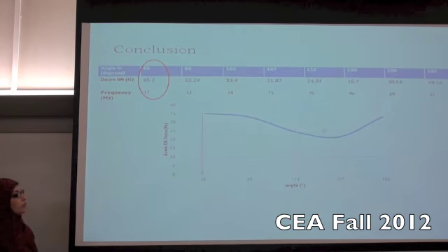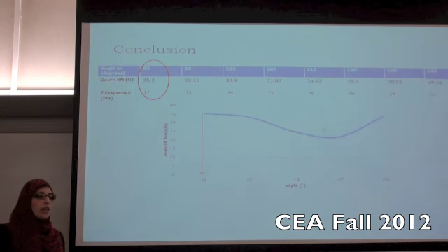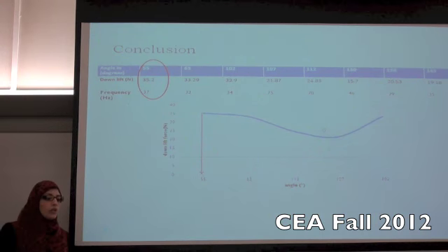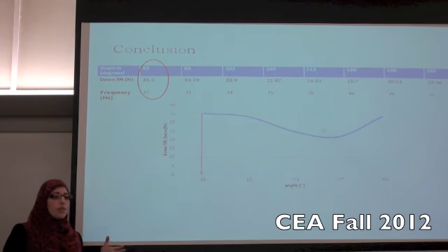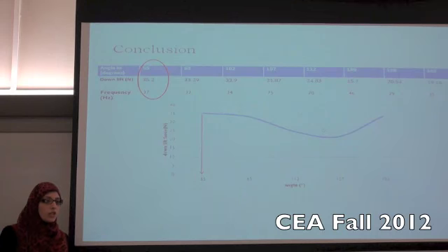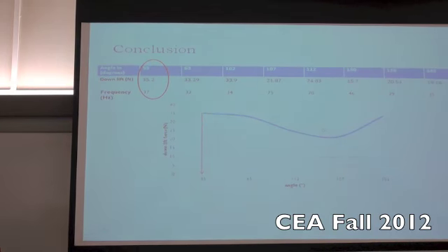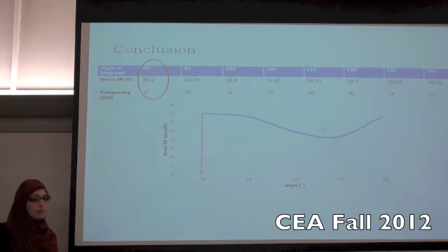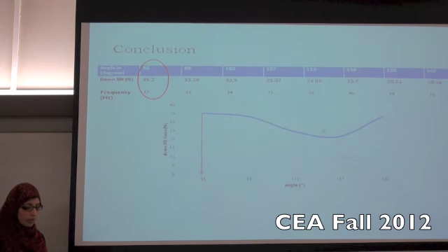Finally, after running 8 different angles, we got that angle 55 gave us the maximum downward force, and its frequency is different from the natural frequency of the bridge, which ensures the stability and an unobstructed behavior. Thus, we have a safe and stable bridge regarding the aerodynamic response.